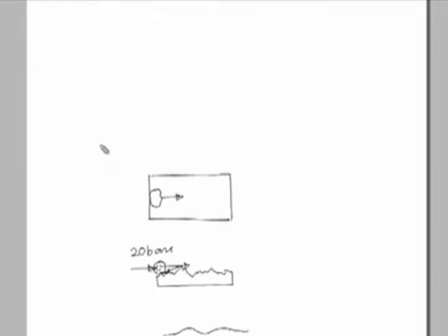Then in some cases, if we see the other view of this, the abrasives will impinge on this and cause plastic flow of the materials nearby to this abrasive particle. So, this is the abrasive particle and this is the workpiece surface, and there are plastic deformations in the sideways of this abrasive particle.